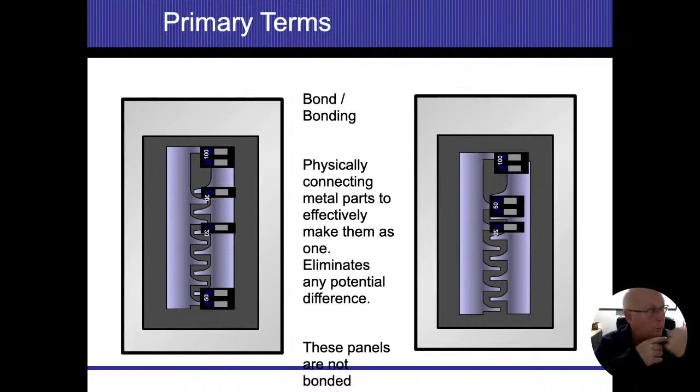In my home, my disconnect is located outside in the meter panel. So I'm going to have a grounding electrode conductor coming out of that and going to my water pipes. I actually have a secondary ground that goes to a ground rod right below it. Even though it's tied into my distribution panel, my main distribution panel does not have another bond in it. My grounding electrode conductors go from the first means of disconnect. In my case, it's outside. In most homes, it's going to be wherever the main panel is located, at that first main disconnect. The two systems that we're connecting are my grounding system and my neutral system.